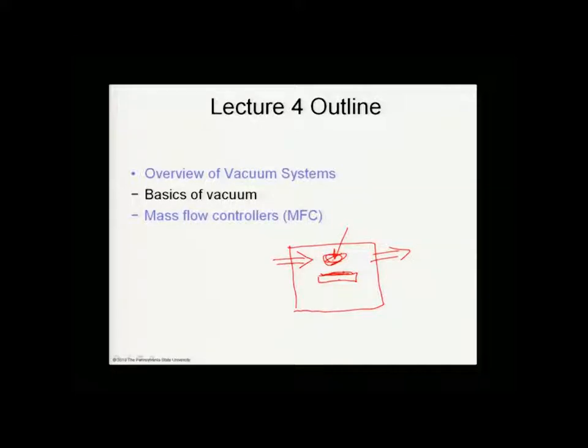We talked about evaporators in lecture 3. Generally speaking, we don't want to introduce a gas unless we're going to evaporate something. I think we mentioned evaporating titanium, for example, and we wanted to form titanium oxide. Then we'd want to evaporate the titanium and introduce oxygen in. So even in simple physical vapor deposition situations in a vacuum system, we may be interested in gas flow.